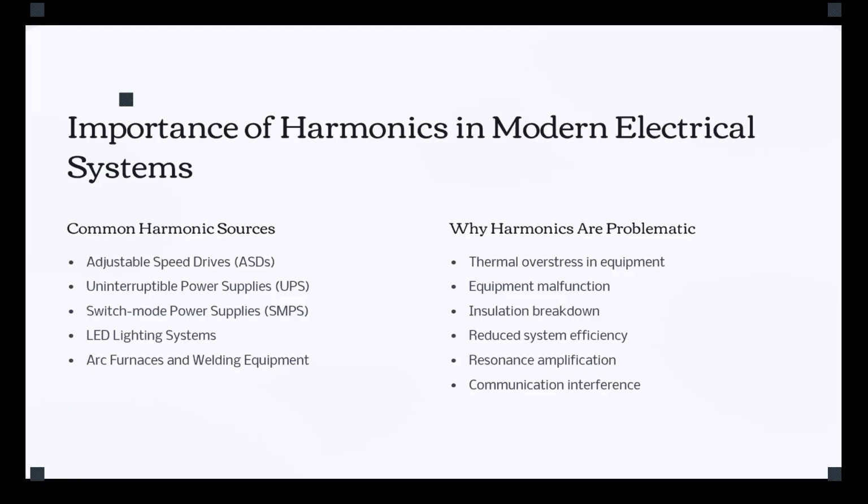Okay, so you can imagine that because our system works with that fundamental frequency, with that 60 hertz, and it is designed to consume and work with only that, all the energy that is stored in the other harmonics is basically useless for us. Okay, so they are basically energy losses. So that would reduce the efficiency of our system. And it's not just these problems.